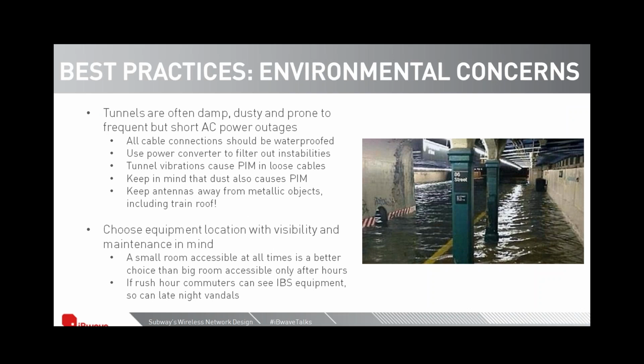And then this is a very important topic, environmental concerns. Tunnels are often damp, dusty, and prone to frequent but short AC power outages. Because of that, all cable connections should be waterproofed, all remote units should have backup battery power, and power converters should be used to filter out power instabilities.